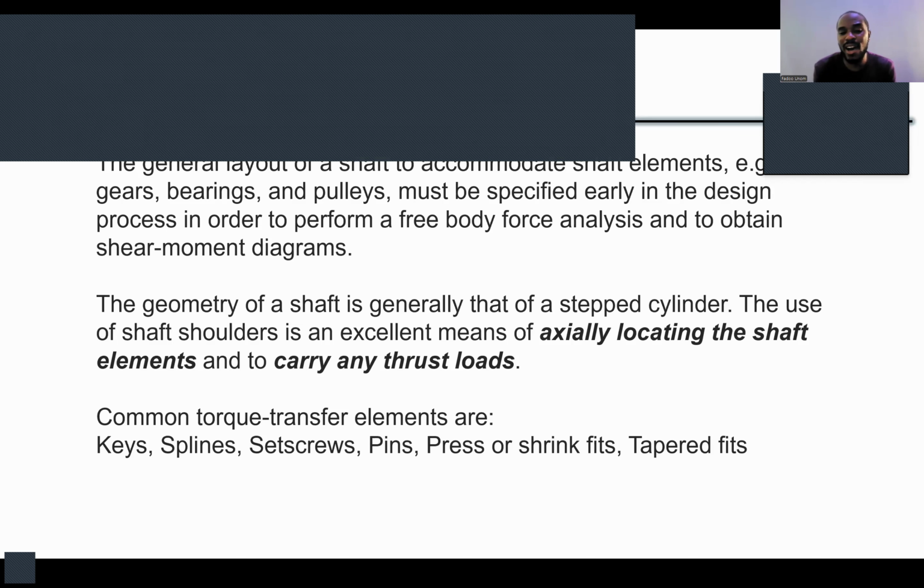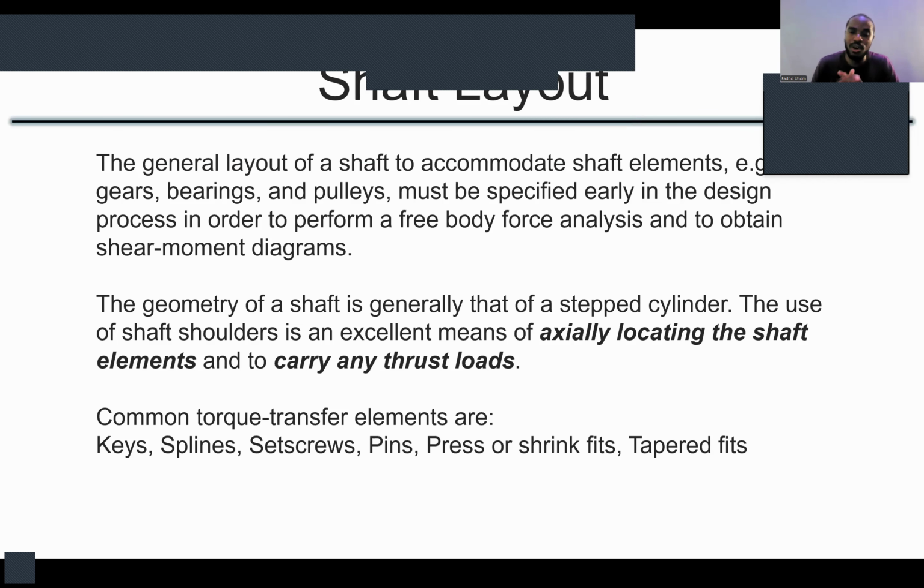And then the other function that they do is they allow us to carry thrusts. Thrusts are loads that are transmitted along the length of your shaft. So thrust loads are axial loads, particularly when you have helical gears. You have gears where the tangential force being transmitted is not perpendicular to the axis of rotation. They are inclined at an angle. Those gears have forces that act both radially and axially.